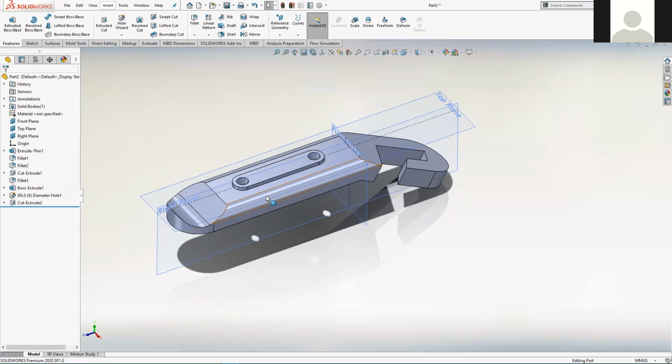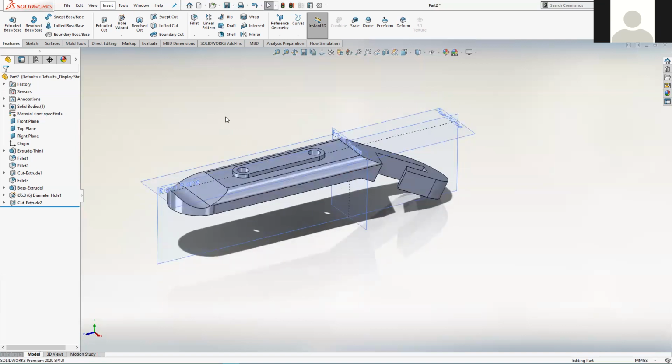And as long as each one knows where the other folder is, everything is fine. But it just overcomplicates things at this level. Just keep all your parts and all your drawings in a single folder. Just dump them all in together. And you'll not run into any problems in terms of drawings not being able to find their corresponding parts.